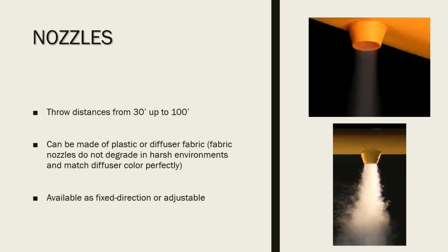So you have manufacturers that do use a textile nozzle option, which is ultrasonically welded to the fabric duct itself. It's made from the same fabric as the diffuser, so it will always match the color, and it will always keep the same continuous UL rating because you're using the same fabric as the diffuser itself.